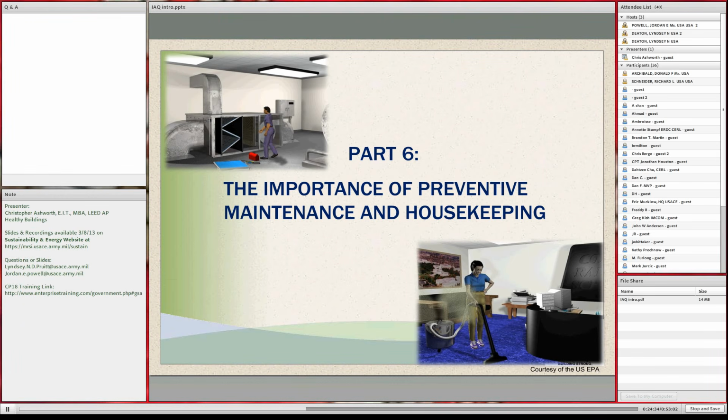Just today, as an anecdote, I got a phone call from somebody from a tenant build-out, and we had done a focused indoor air quality study on it. And they hadn't done enhanced commissioning, hadn't done any commissioning on the tenant build-out. When we were on site, we noticed one little issue: the complaints they kept having about dust in the space itself. And it turns out that on the return air ducts during the construction process, they put really good zip filters on them, which was great, but they never took those off. So the filters were caked with dust and dirt, etc.